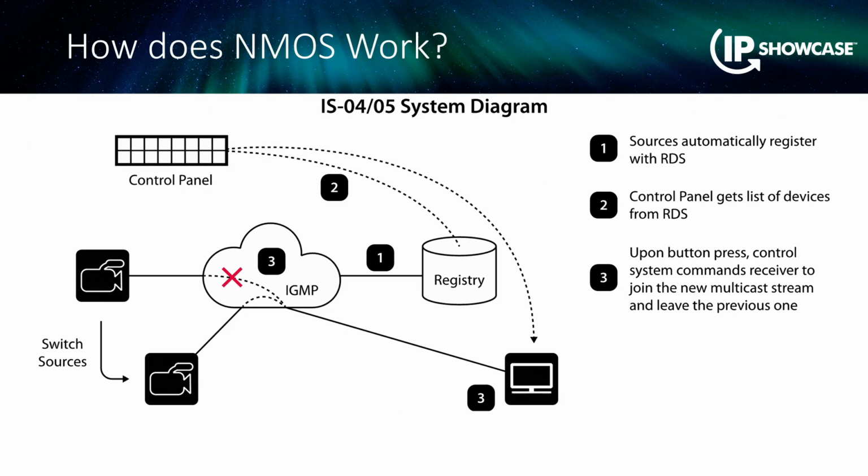So what happens when somebody does that? Somebody says, I'm currently connected camera 1 to the monitor, I want to connect camera 2 to the monitor. How do we do it? Well, we do destination monitor 1, source camera 2, take. That sends a message to the receiving device, this monitor here, and it says, please, Mr. Switch, Mr. Cloud in the middle here, give me that stream, right? These cameras are all transmitting their streams normally, but the switch stops them. It's not going to send everybody unless you ask for it. So the monitor says, hey, I'm going to do this IGMP join to that stream. And by the way, disconnect me from the other stream. You can do it before or after. There's a few ways to do it.